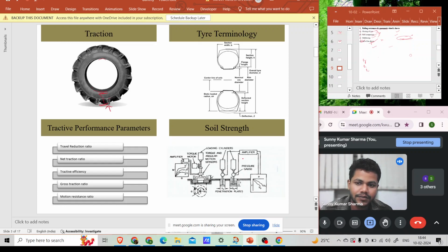That is the carcass pressure, PC. Inflation pressure is inside this carcass. That is PI. If the combined PI plus PC is greater, then the wheel will not deflect against the ground and it will operate in rigid mode. And if this is less than the ground pressure, meaning the ground is applying more pressure, then it will deflect and it will work in elastic mode. Is it clear?